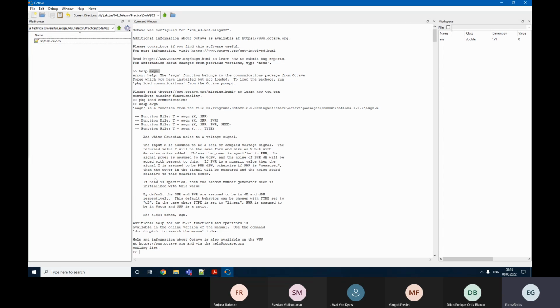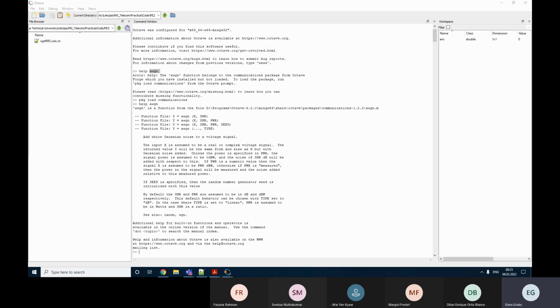And let us start with the idea of what we are going to do today. So what we want to do is to simulate the operation of quadrature amplitude modulation with 16 signals. Yes, so the regular constellation should be already familiar to you from other courses. Yes, it consists of 16 equidistant signal points. Yes, like this. So we are going to simulate this by generating some random data, for example, 1,000,000 symbols or 100,000 symbols.